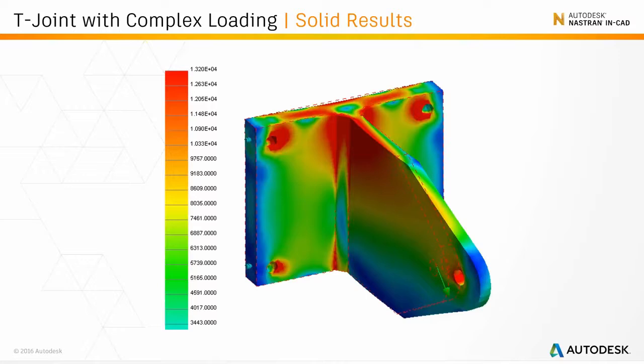So what's the best way of using a solid? Well, really we should be approaching using solids in much the same way as we've looked at using shells. And that is to use the solids to give us further information about the loads that are being passed between those two plates, rather than using them to determine the stress on the welds themselves.